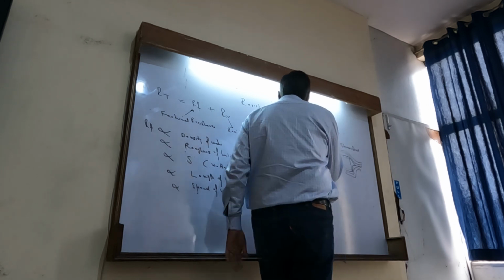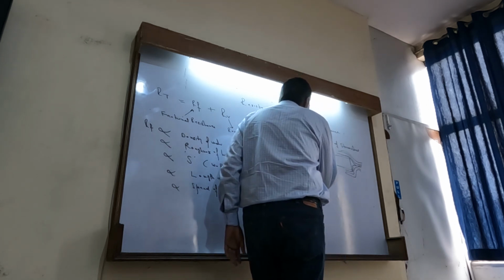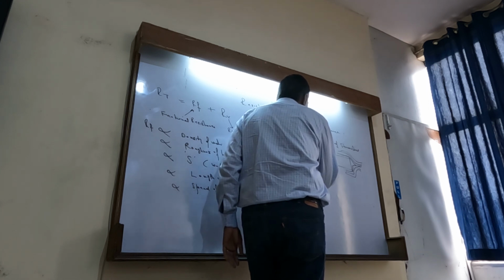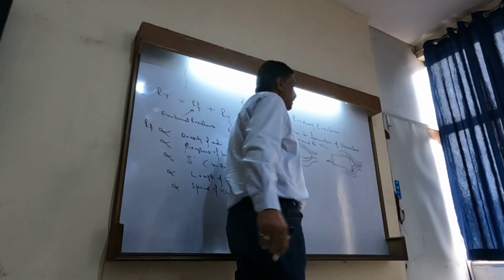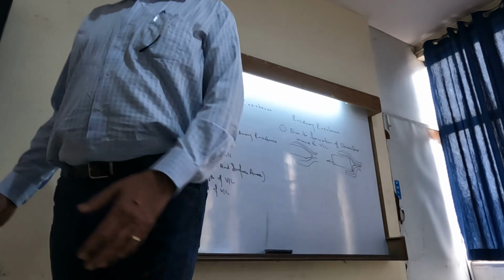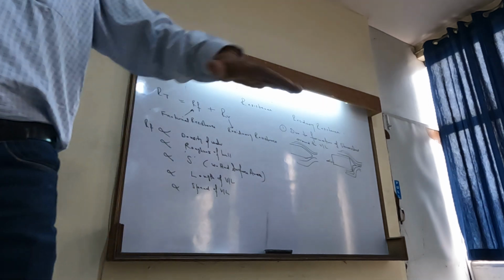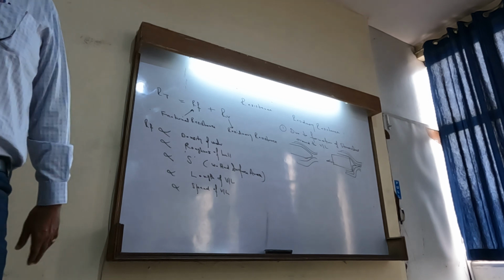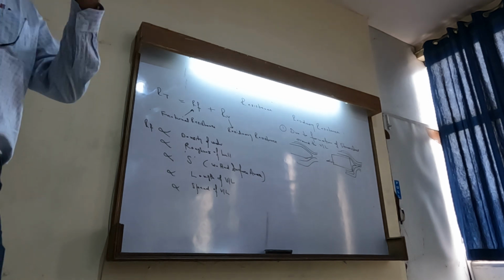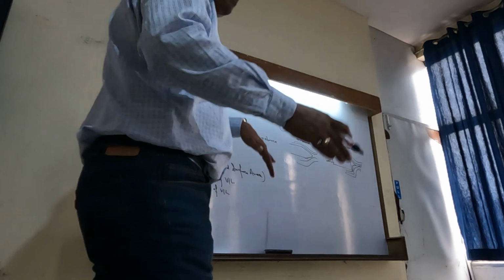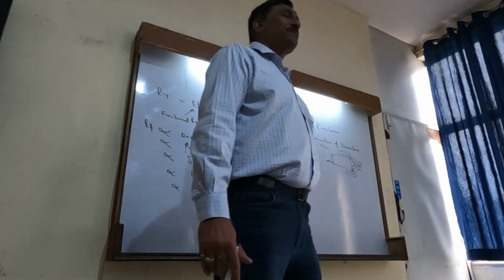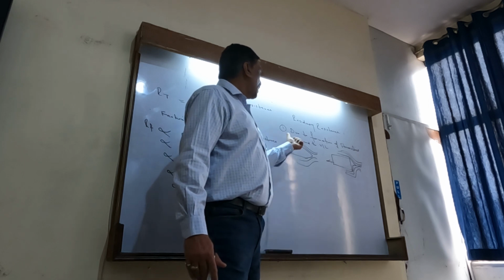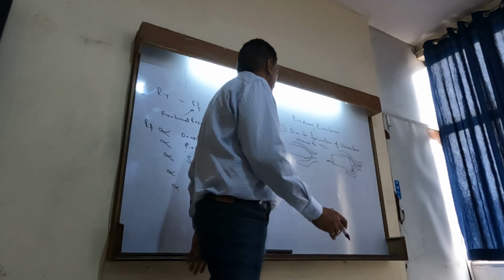However, if it is profiled nicely, then this resistance will be less. If the barge is moving with its front flat, more resistance will be there. If you profile the forward part of the vessel, and that is why we always have very carefully profiled vessels, the resistance due to formation of streamlines is less. That is one part of the residuary resistance.